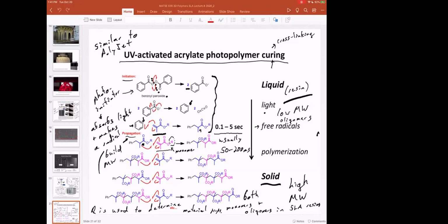I don't know if the printers you've used have used Cura, but you tend to define the different materials when you slice it and when you make the tool path, because the printer has to know what materials are where in order to set up the right machine parameters. And that's done a little bit differently depending on what you're slicing and what your G-code generation software is.